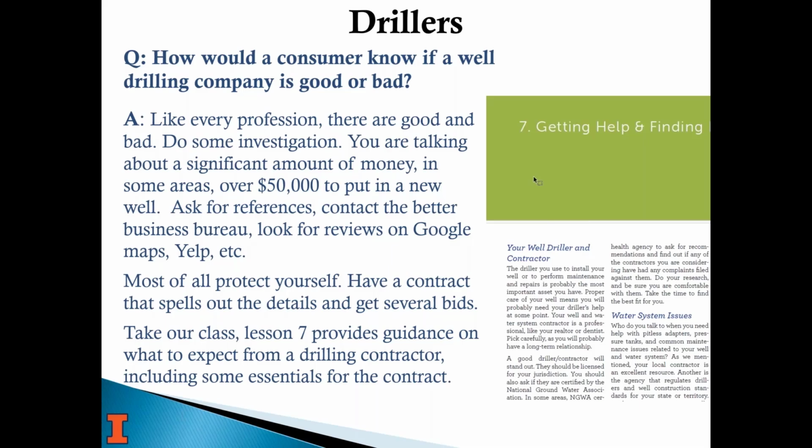It recommends here that you ask if they're certified by the National Groundwater Association. That certification isn't mandatory anywhere, but knowing that they've gone through the NGWA certification process means they've gone to the trouble to take classes and be better informed drillers. If I had two drillers and no other deciding factor, I'd always take the one that went through NGWA's program. But again, lesson 7 has that information. That's all I can say there.